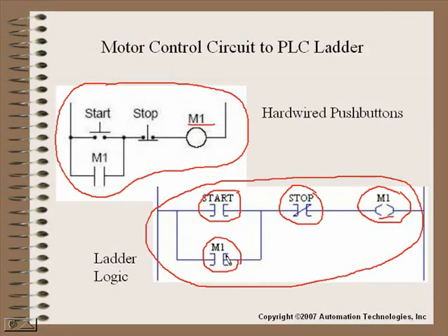Now, actually, I don't like to do this. This is not where we like to stop. We actually like to take this relay coil, take a contact that would come back from that relay coil and then enter that into our PLC program. And therefore, we actually have a real-world understanding when we seal our circuit in. If this relay were to drop out for any reason in the field, then it would also drop our seal in the program.